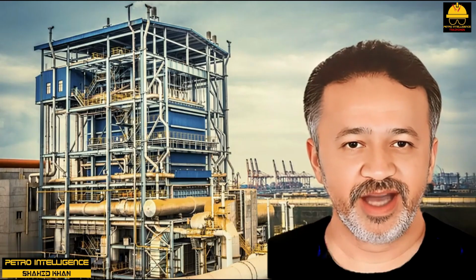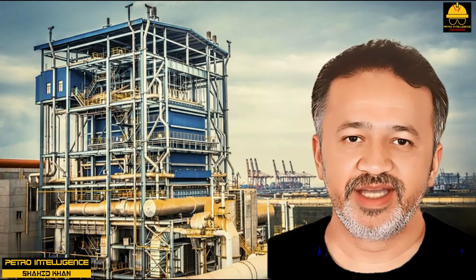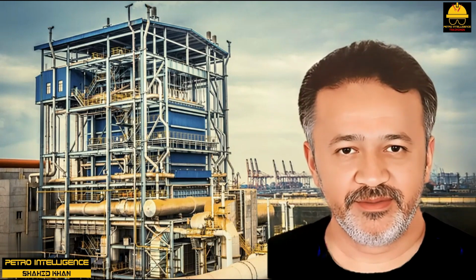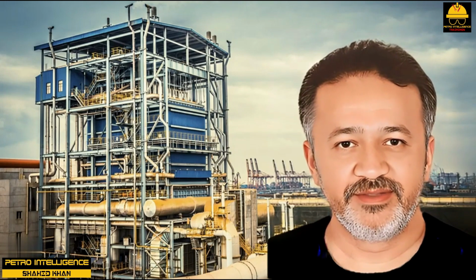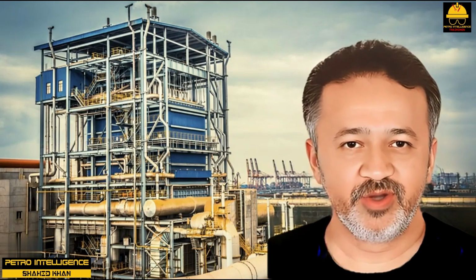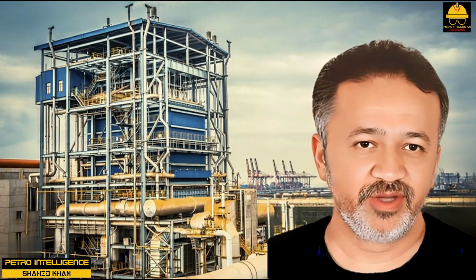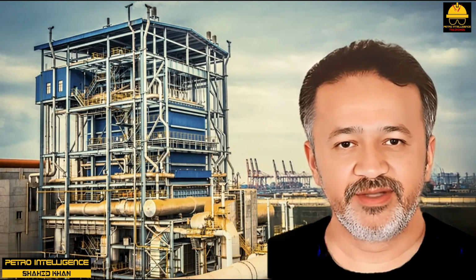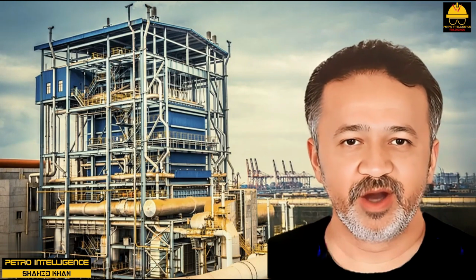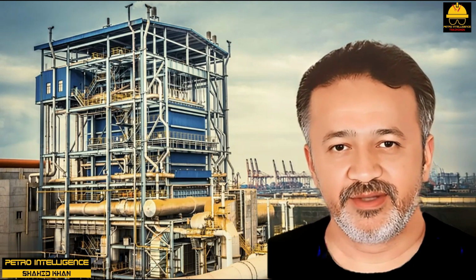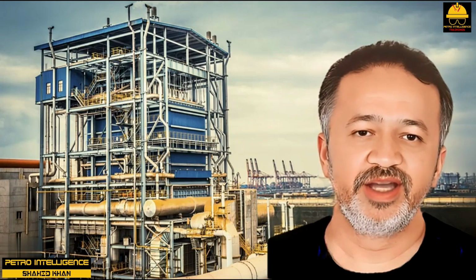Wire spring turbulators may have an advantage over tubes with no inserts in that they keep the tubes cleaner. This seems to work best to prevent fouling if it is as a film. If fouling is in the form of particulates in the feed, then the tubes have a tendency to plug. There is also the effect of increased pressure drop to be taken into account when considering tube inserts as a retrofit. However, the decrease in temperature gradient between the tube wall and the bulk fluid may work well to reduce fouling when the fouling is tube wall temperature dependent. This was seen particularly on a furfural unit when a fixed tube insert was used on the rundown cooler and reduced the storage temperature by about 54 degrees Fahrenheit.